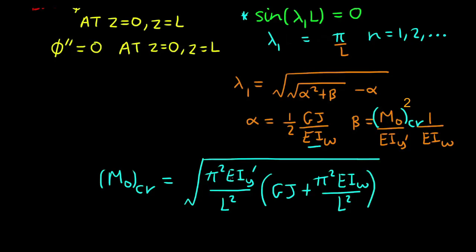So when a beam buckles, it buckles laterally and twists and warps. So this is similar to the Euler buckling load, which we had for a column. So recall the critical buckling load for a column is pi squared EI on L squared, and you'd replace this with the effective length based on different restraints applied to the column. And similarly for a beam, based on different restraints applied to it, you'd replace L with the effective length, where the effective length is going to depend on twisting and rotational restraints.